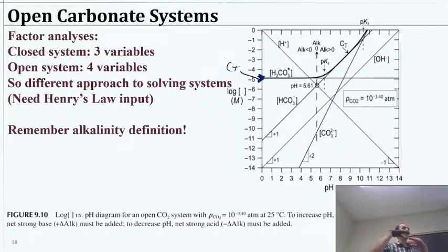That's our equilibrium point with the atmosphere. Now, what's interesting is as soon as we start shifting higher in pH, and we start getting some other forms of carbonate, more CO2 from the atmosphere comes back into the water. We're going to assume the atmosphere has a constant amount. We're not going to deplete the atmosphere of CO2. Maybe globally the oceans could make a difference over time, but in my bottle that's open to the atmosphere, we're not changing the amount of CO2 in the atmosphere.